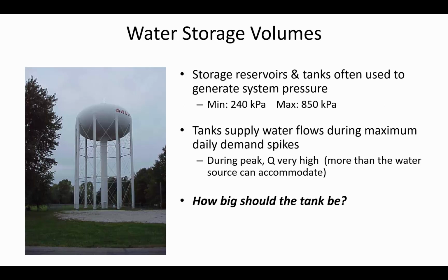So part of the reason why we have this reservoir or tanks that store finished fresh water is to make sure that during these periods of high flow demand that we have enough water at the ready to supply the demands. So we may have water coming in at a constant rate and then it's coming out of the reservoir at a variable rate.